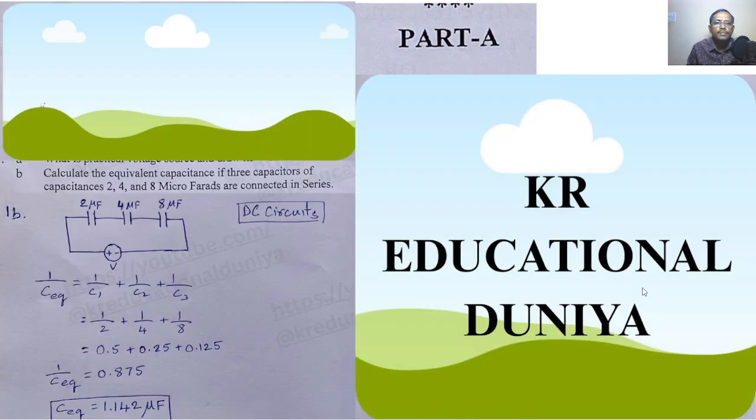Next question. In 1b, calculate the equivalent capacitance if 3 capacitors of capacitances 2, 4 and 8 microfarads are connected in series. Here, when capacitances are connected in series, we use the formula 1 by C equivalent equals 1 by C1 plus 1 by C2 plus 1 by C3.